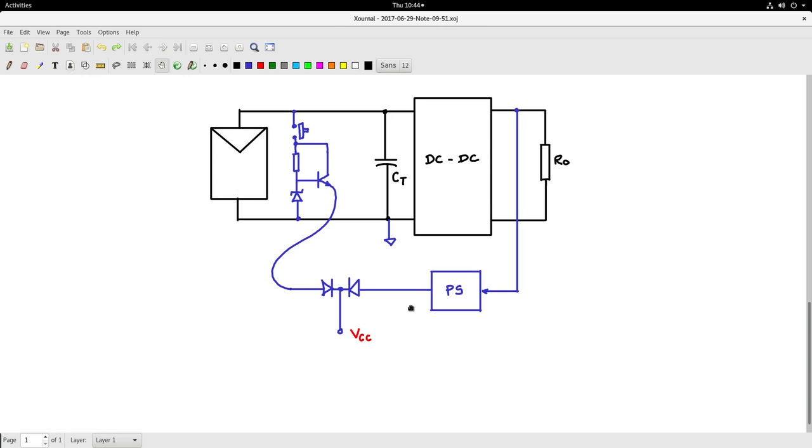So how will this operate? During the start, you will see that there is no power for the DC-DC converter. So therefore, the output of this power supply is also low. So what I will do, I will press this reset button. You press the reset button, there is voltage applied across this resistance Zener combination, and this will be at some potential. Now let us say I will keep this at 16 volts. Now 16 volts minus 0.7 will occur here, because this will now be in the linear region. 16 minus 0.7, 14.3, 14.3 minus another 0.7 will be 13.6. So 13.6 will appear across here.